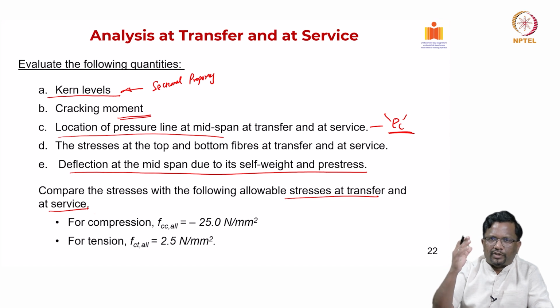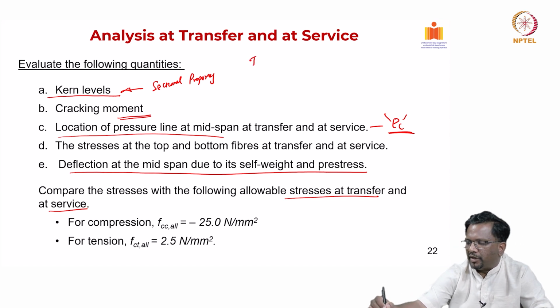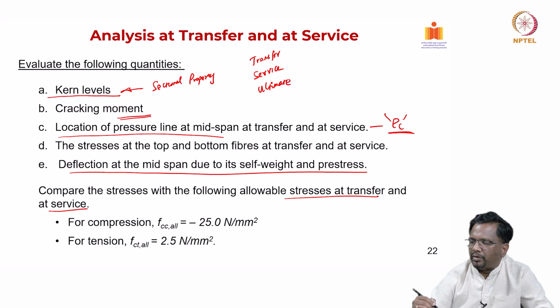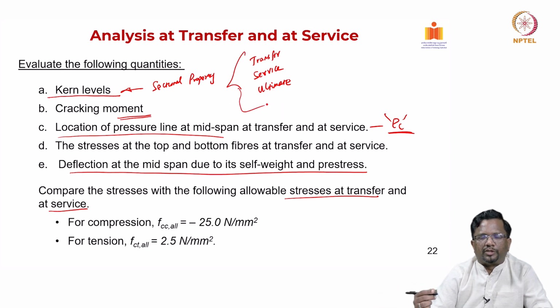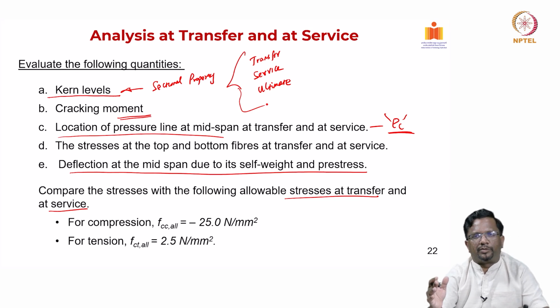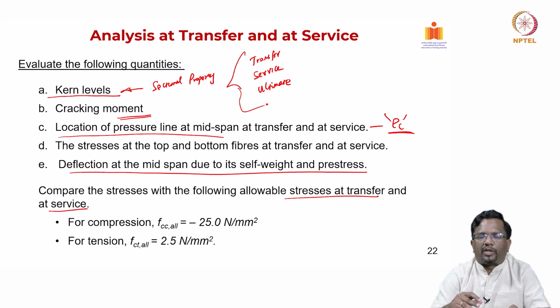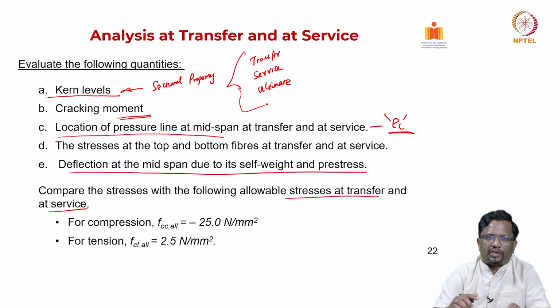In pre-stressing, we have always seen there are 3 stages: transfer, service and then ultimate. In RC, typically we will have only 2 stages, service and ultimate, but in pre-stress we should also do the analysis at transfer. That means when you transfer the pre-stress, what kind of loads are acting, all those things we have to consider, and these are the stresses in compression and tension. Now, let us see how to do the analysis.